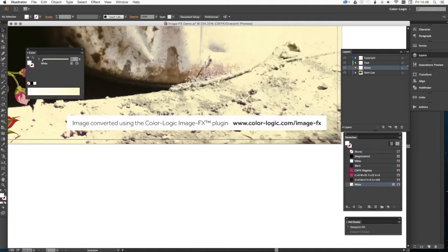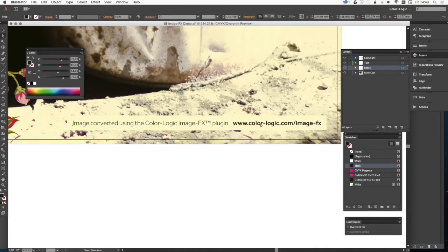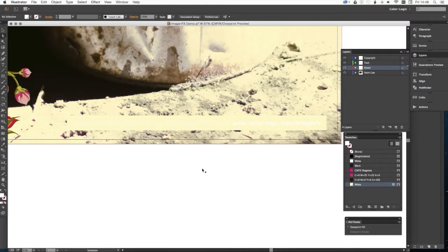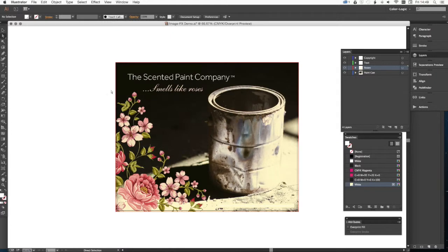So down here, this box, which is white, needs to be white ink, and the text we had as silver. So if I want that to be silver substrate, you need to put the white ink, change the value down to 0. So then what happens is the silver substrate shows through. So there we go, quick and easy-ish, creating white ink plates, and there we have our two files.